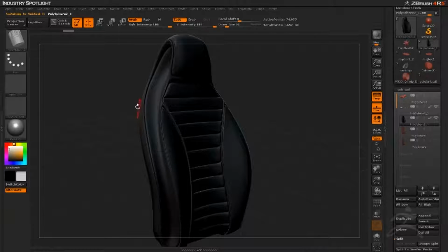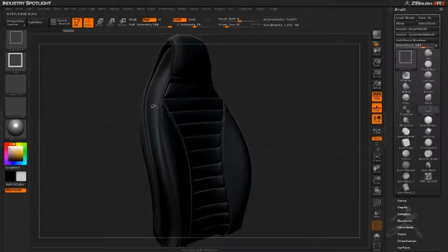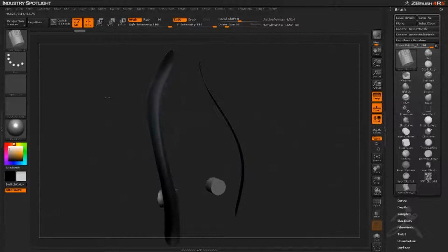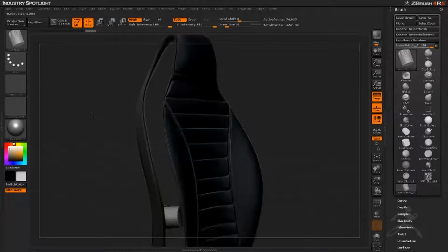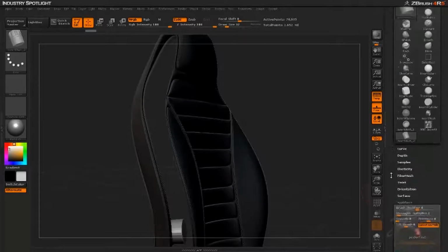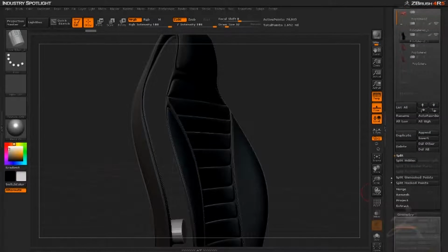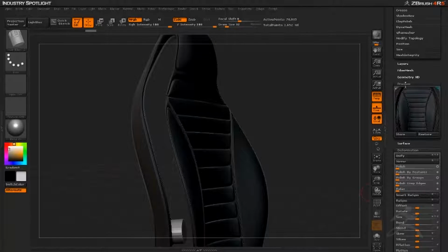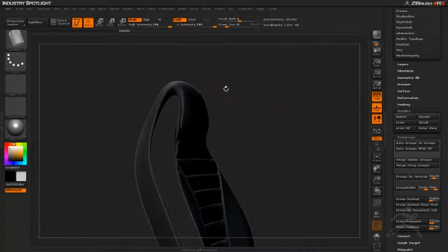So this piece right here, oops, come down here to Control and Shift, select Rect, there we go. And swipe that. I think this could go out quite a ways, so I'm going to shrink the selection until it gets about where it should be. So under, wow, deep down in here, under visibility, I think this whole area in here should all be metal, so continue to shrink until it gets out to where I think it should be.